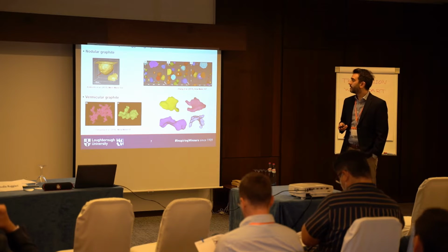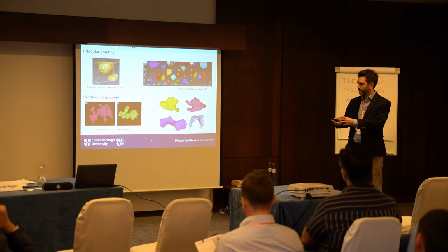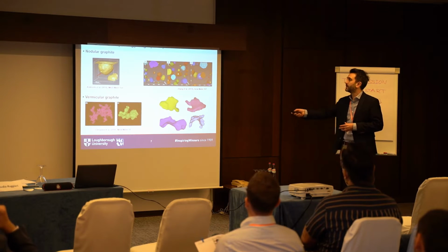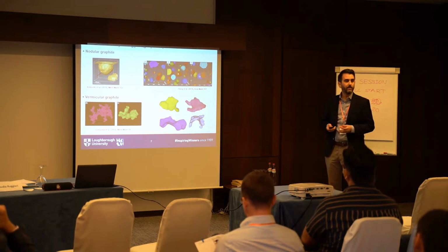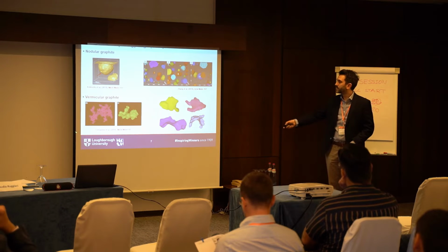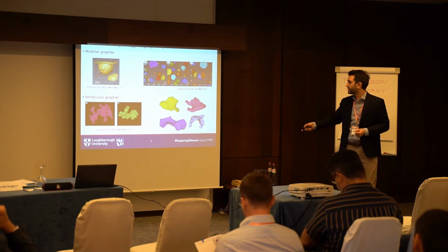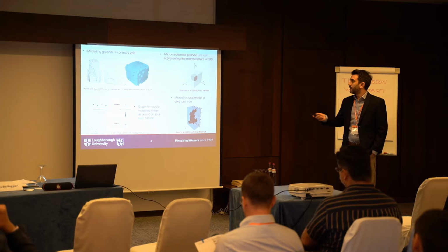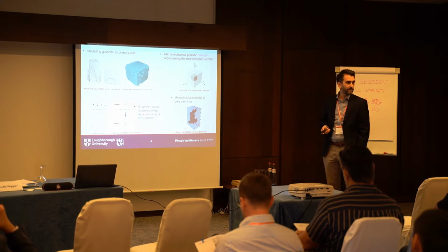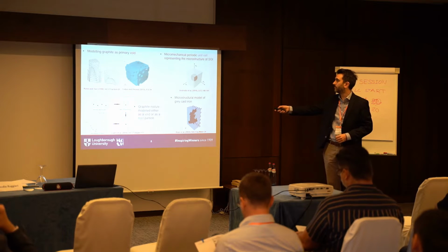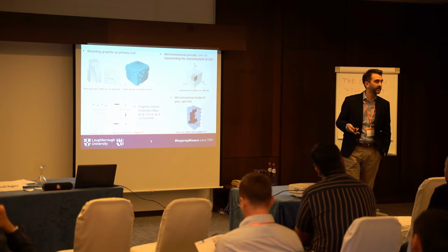Another parameter for the modeler is how these particles look. In the top row of the studies, what you saw in the micrograph as a circle is essentially a sphere, but not a proper sphere. If you look at this vermicular particle, which I said looks like a worm, essentially it is a cloud, or a coral in the sea, I don't know how to call it. These are some CT scans. So it's no surprise that modeling attempts neglect these particles completely. They say it's a void and only deal with the matrix, or they take a perfect circle, or even rigid inclusions, and so on: simplifications.